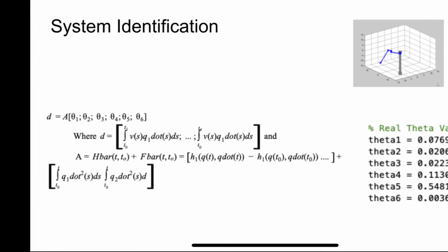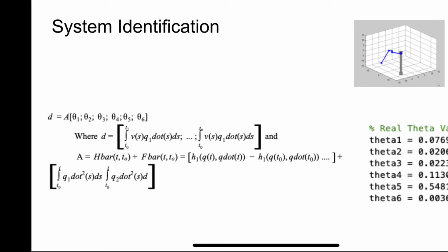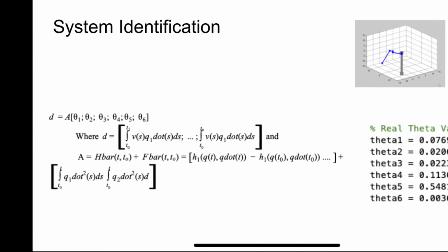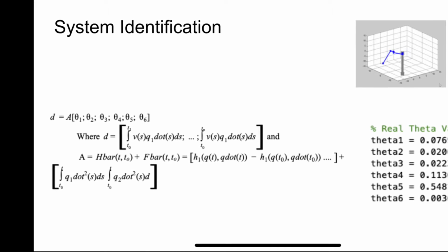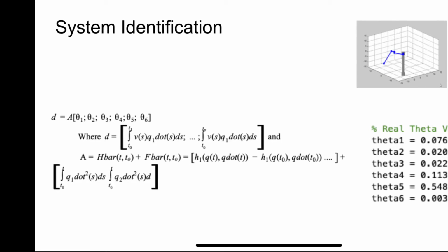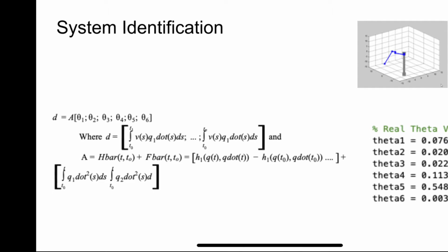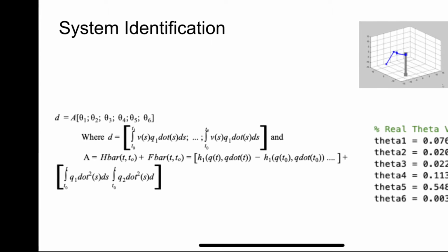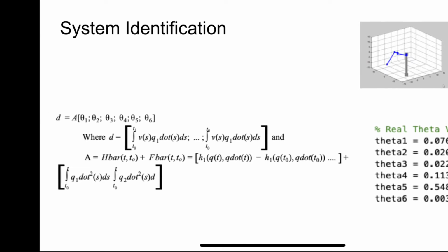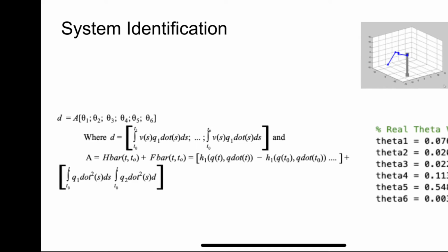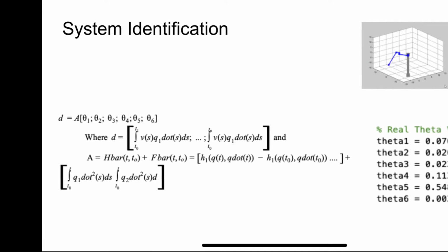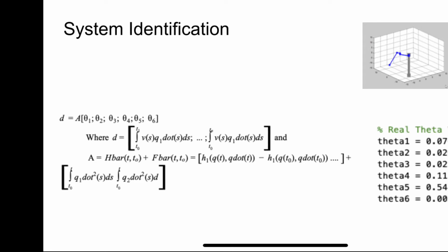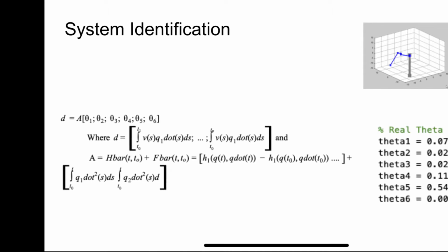We implemented a function to output the physical parameters of the system by converting the conservation of energy equations into a matrix form that would be able to calculate the 6 theta values from a data set of 10,000 points. To test the accuracy of using a Hamiltonian energy approach to estimate theta values, we collected data from our simulated robot to show that our function would produce the same as previously calculated theoretical thetas. We then used this function to experimentally estimate the physical parameters of the real system.